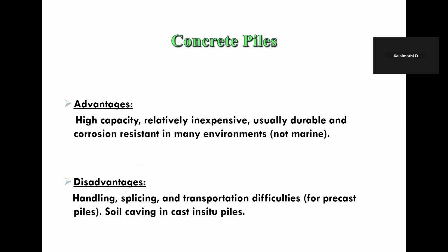So most probably what we are using is concrete piles. They are inexpensive, usually durable, and corrosion resistant. The only disadvantage is transportation difficulty, especially with precast piles. So usually we will cast piles in situ.